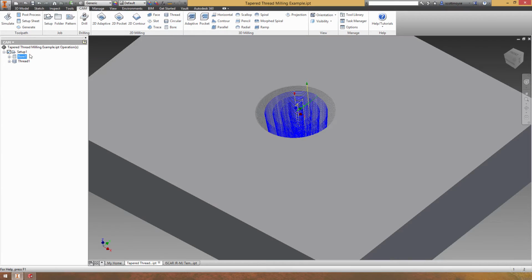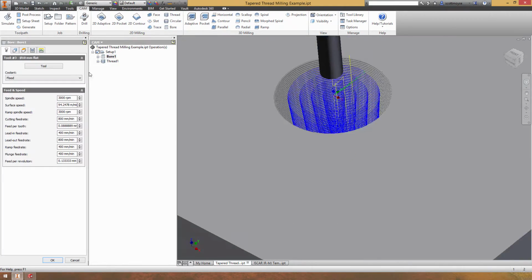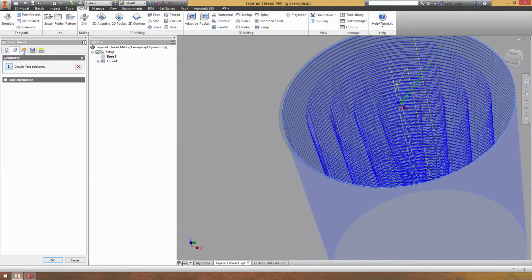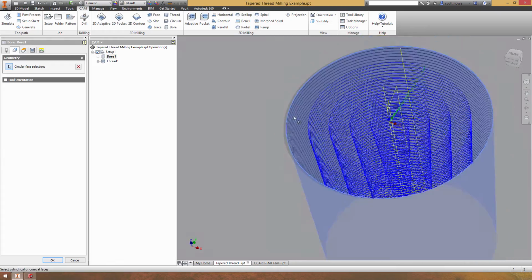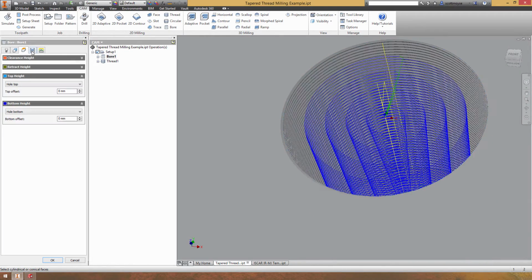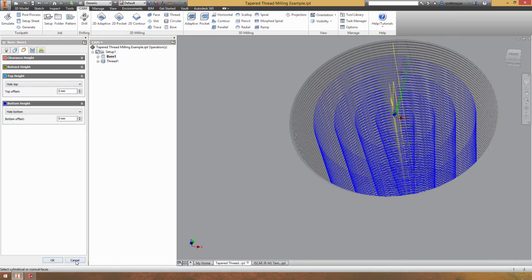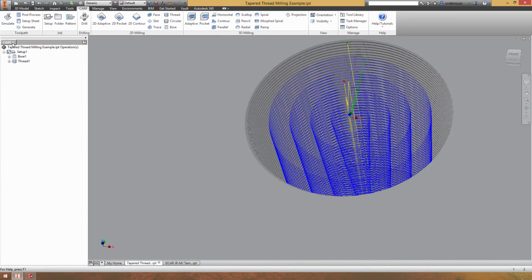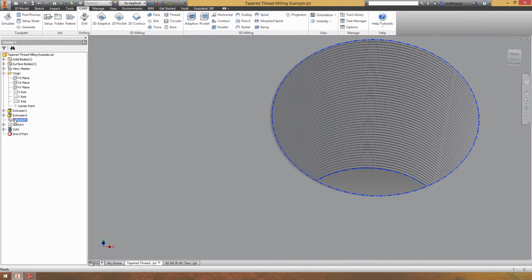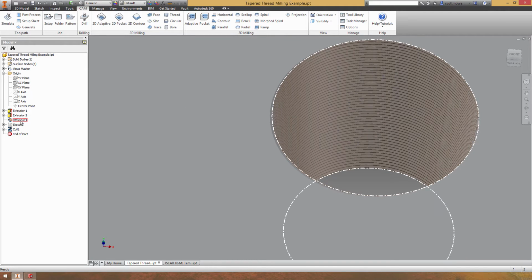strategy here. I used a 10mm flat tool. You should use a boring tool, but I haven't in this case. I've selected the conical face in here, and in actual fact, I'll just take a couple of steps back because I've modelled this thread. Before I modelled it, I offset the surface by 0mm so that I could use that surface to define my toolpath later on.